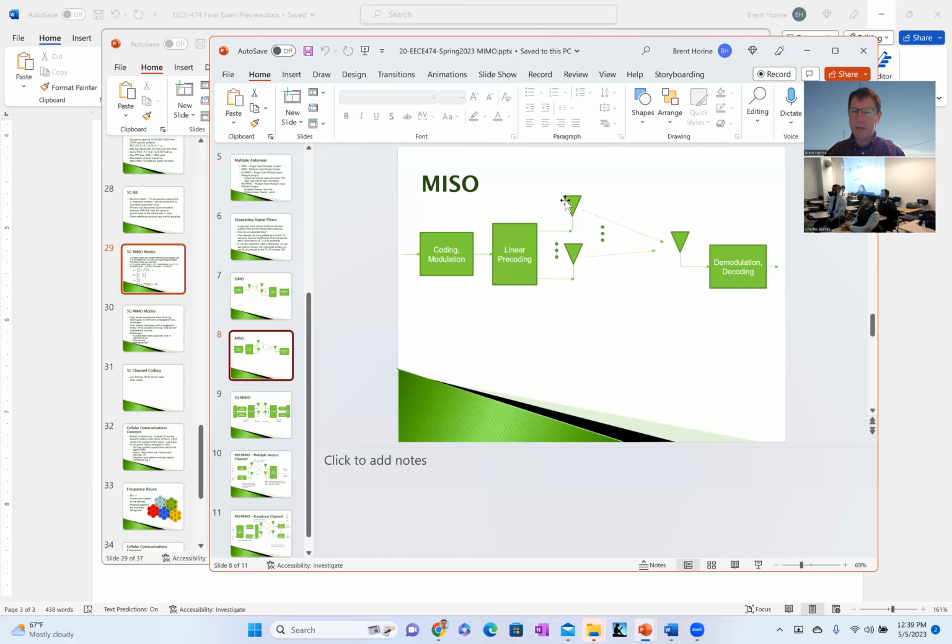So at one instant we'd send the training symbol or reference signal for this antenna, and then maybe a few instants later we'd send this one, right? Typically we're only sending one at a time, and so the receiver can measure that ray at that instant, and then in the next instant or the next known location of these reference signals, it will measure that one.